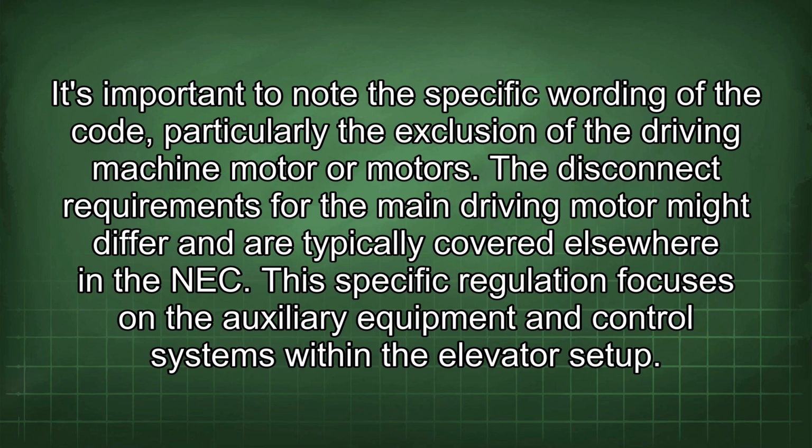It's important to note the specific wording of the code, particularly the exclusion of the driving machine motor or motors. The disconnect requirements for the main driving motor might differ and are typically covered elsewhere in the NEC. This specific regulation focuses on the auxiliary equipment and control systems within the elevator setup.